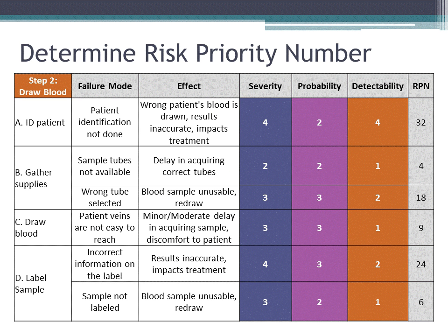Okay, so here we're moving back into our example. For each of the failure modes that we thought of before, we've assigned a severity, probability, and detectability score. Then we multiplied those scores together, and we calculated a risk priority number for each failure mode. This concludes our hazard analysis. We've done the qualitative part of it, and then we finished up our quantitative part of it. We've determined a risk priority number for each.